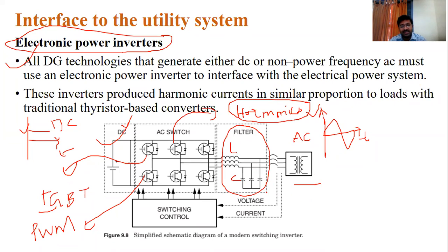But the installation cost of this type of filter is very high. You know that when the rating of the inverter increases, the rating of the filter also increases. That may lead to a cost problem, increasing the cost of the inverter and everything else.